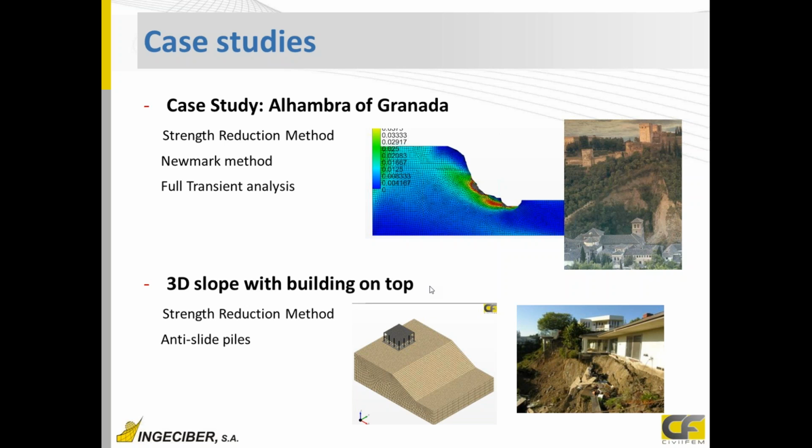We consider always that these methods that will be presented today are more accurate than the classical methods that already everybody knows. In all the classical methods, the slices are taken into account, and forces and equilibrium are taken on each slice, and you have to create the circles and tangents, and after that you obtain a safety factor as well.